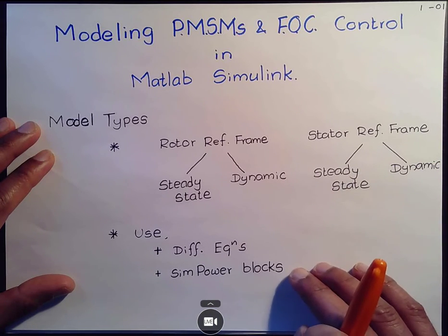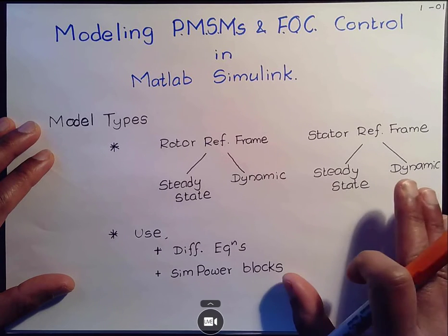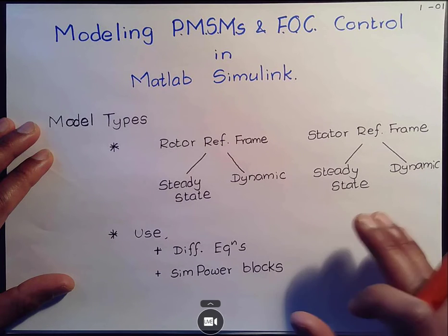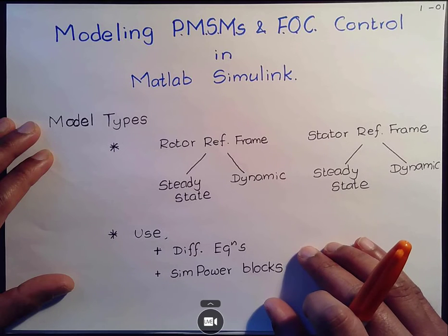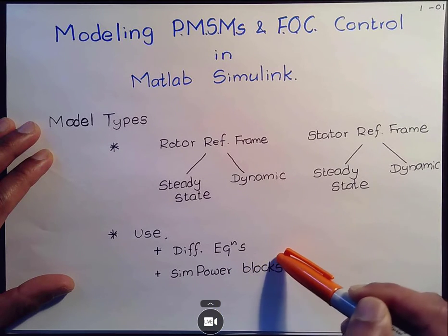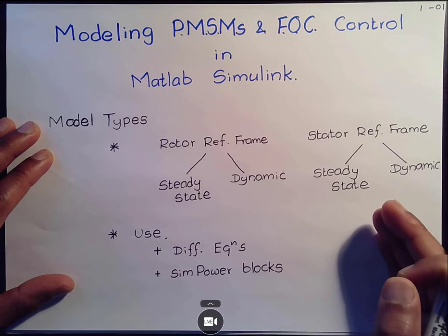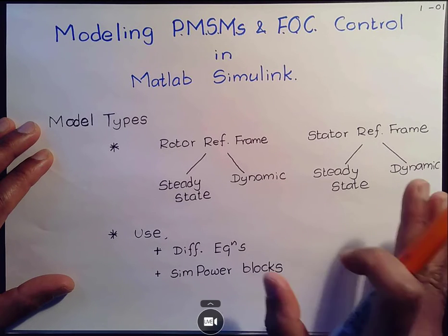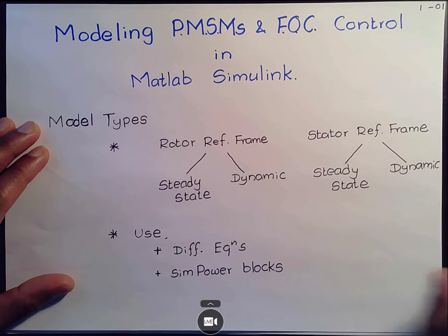Alternatively, you can use the SimPower toolbox. This toolbox that's provided by MATLAB has a lot of features. You can even go into implementing an actual inverter. It does take some time for the model to run, but it's a good representation of what you see in a practical system to a certain extent. But you do have to pay extra for the SimPower blocks if your school doesn't provide it. If you don't have that, don't worry, you can still use differential equations to model your motor.